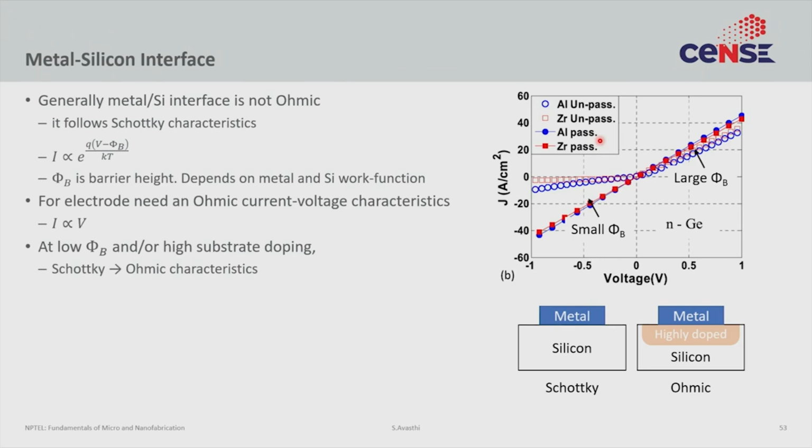So, the simplest metal junction would be metal deposited on silicon, but that is not what is commonly done when the goal is to make a good contact. What is typically done is you take silicon and you grow a very highly doped layer of silicon. So, if this is n-type silicon, this highly doped layer must also be n-type silicon. So, n++ silicon and then the metal layer.